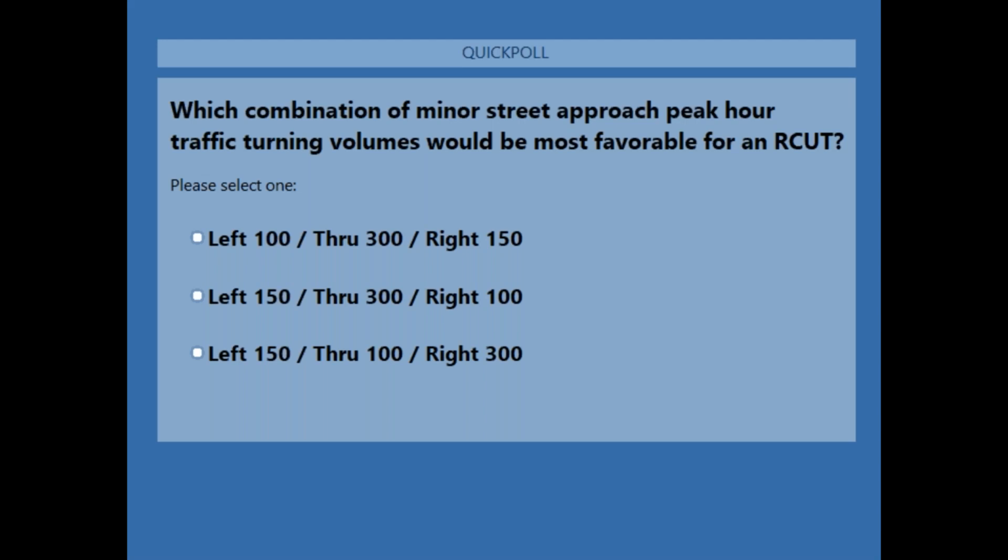So to design for that slower moving piece of equipment, allow them to ride the U-turn lane, make the U-turn, and then what agencies sometimes do is reinforce the shoulder or lengthen the shoulder on the other side so that, again, the farm equipment doesn't have to take a lane. They can basically ride down the widened shoulder or the enhanced shoulder to get to the minor street. So that is one strategy that some agencies have utilized to try to design for the larger or slower farm equipment. Great question.